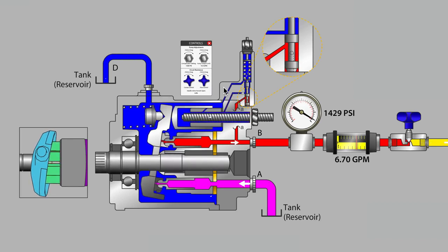And then also consider the pressure compensator, sometimes referred to generically as the controller on the pump. In most cases, the controller on the pump requires a flow of fluid in order to carry out its basic functions. And indeed, you could see flow is taking place. Well, when the pump is in the mode where it is pressure compensating, outlet fluid is being pushed into the control piston. But when the pump is coming back on stroke, oil that was in the control piston has to be ejected. So quite often when you read a piston pump manufacturer's notes about their design, they will refer to controller exhaust that will be present on the case drain line.